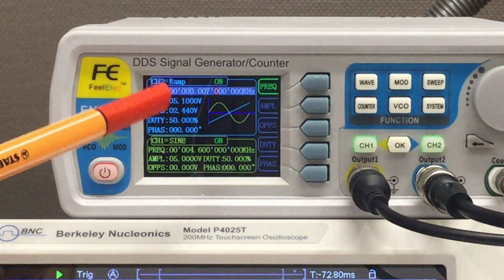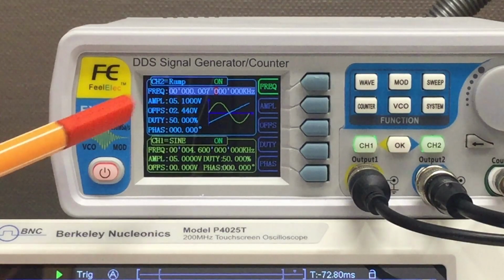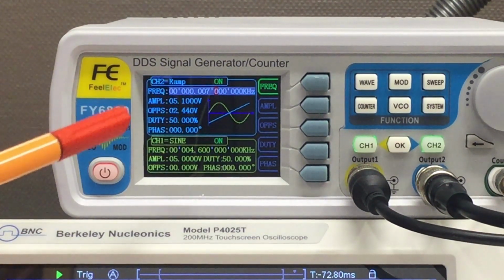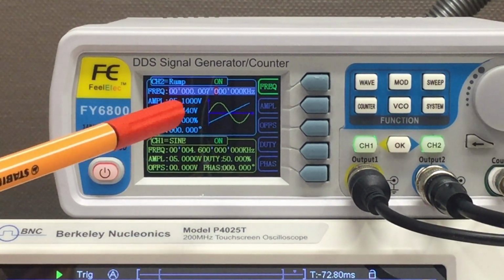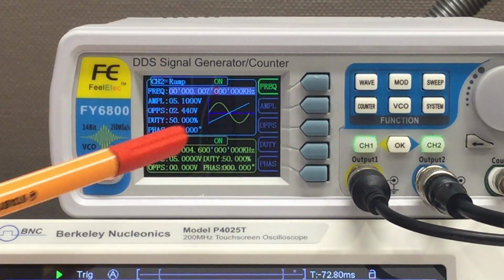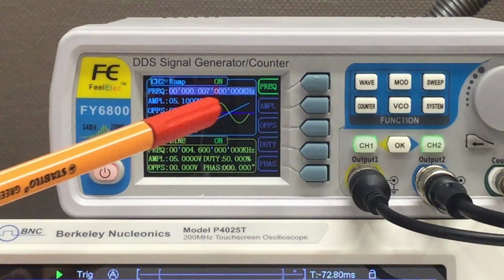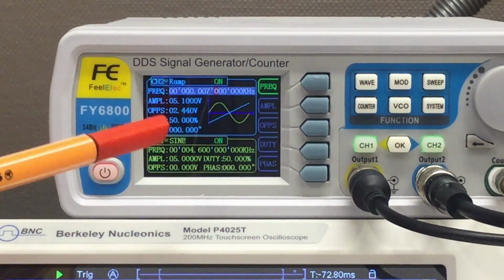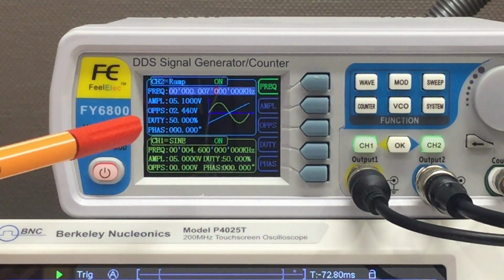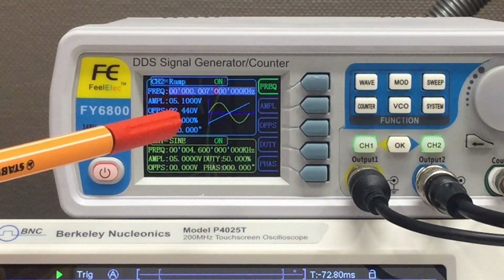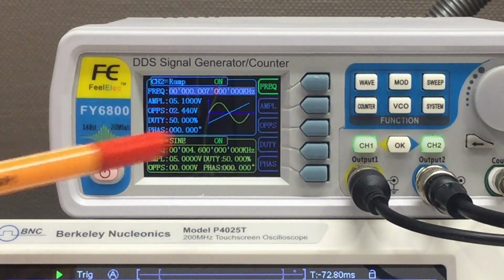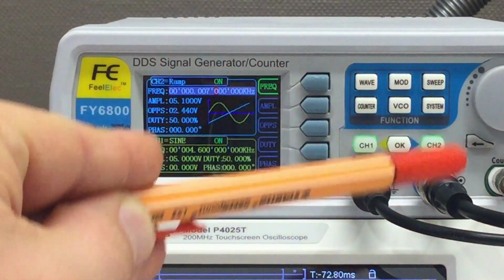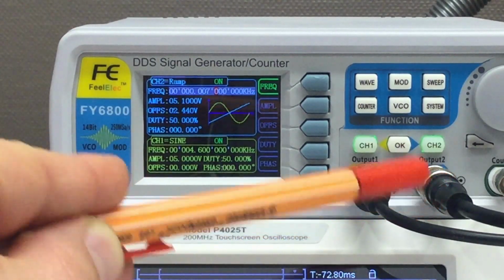And these are my settings for channel 2. So waveform ramp of course, and frequency 7 Hertz. My amplitude is 5.1 volts. And forget about all this decimal precision stuff here. It doesn't really work. And offset 0.244 volts. Okay, let's feed that signal now from channel 2, not only into the oscilloscope, but also